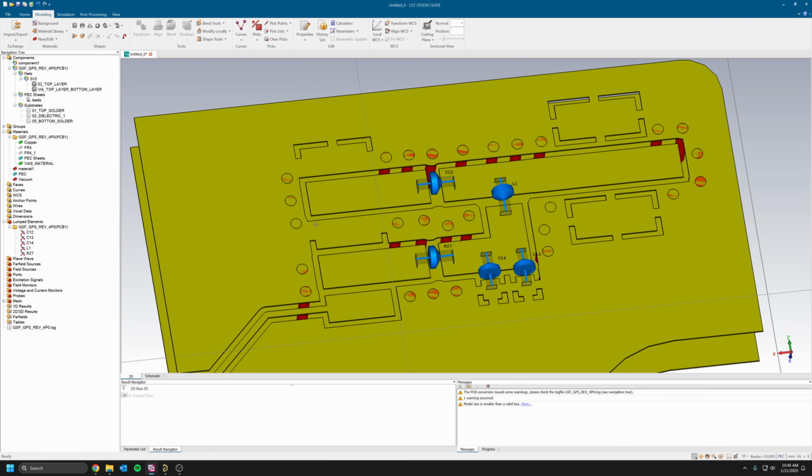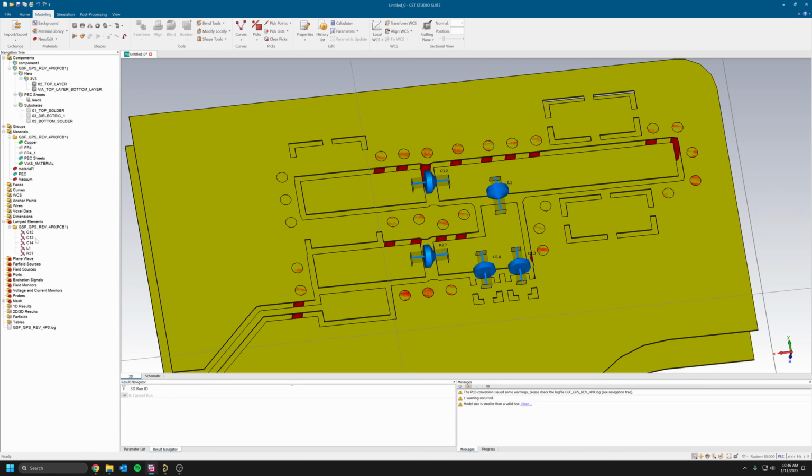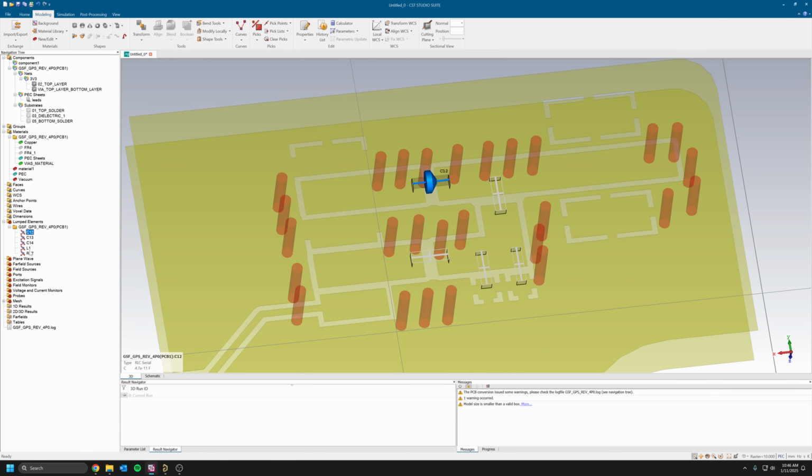So what we're going to do here is start putting some ports. And actually, I might also want to remove these ports, even though earlier I kept them. I want to remove these because they are lumped elements, and lumped element means a fixed element, for instance, a 100 ohm resistor or a 1 microfarad capacitor. But in my case, instead of importing them in my simulation, I might just want to create a port and then add it later in, let's say, my ADS simulation, and then I can fine-tune what capacitor value would be best.